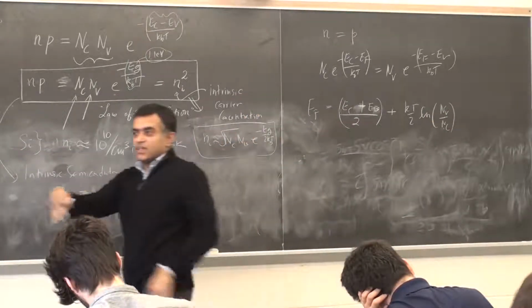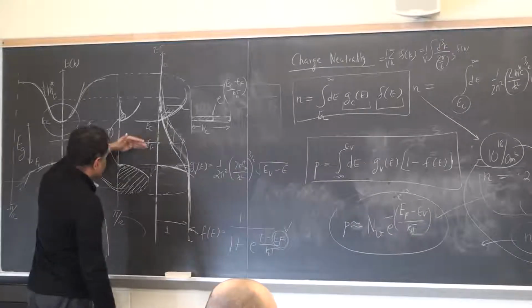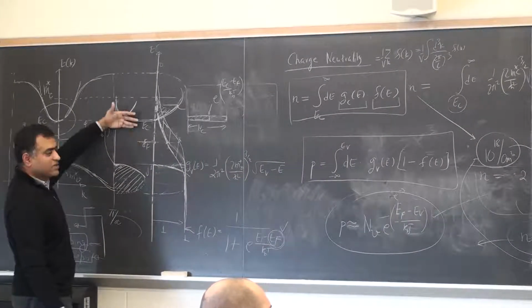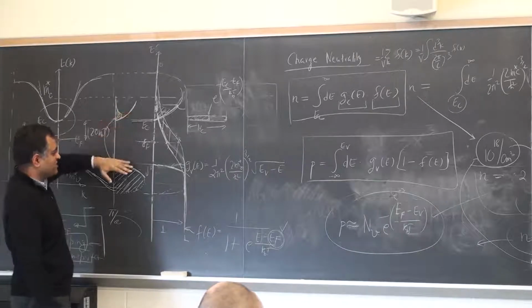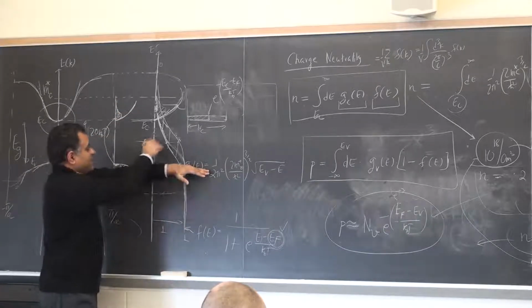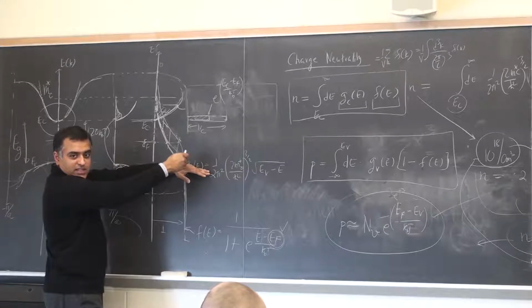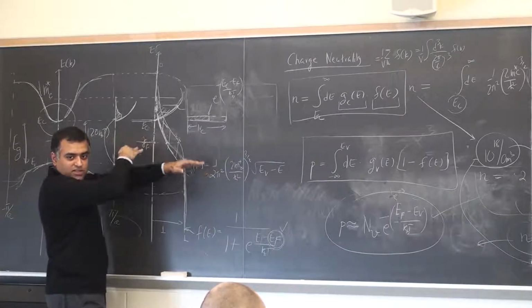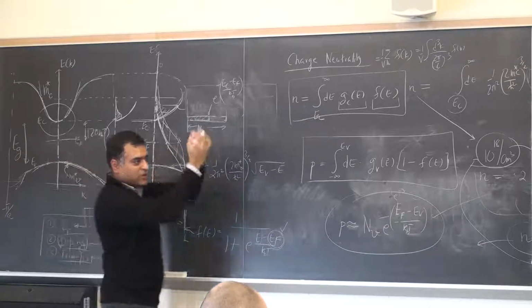If the valence band has a larger density of states, NV is larger, the Fermi level will move down a little bit. If the conduction band density of states is larger, it is going to move up a little bit. I think it makes sense because if the density of states is larger, it can hold more electrons. So if the Fermi level was exactly in the middle, I'd have a charge imbalance. It's also the seesaw mechanism again: the larger DOS pulls the Fermi level closer to it.